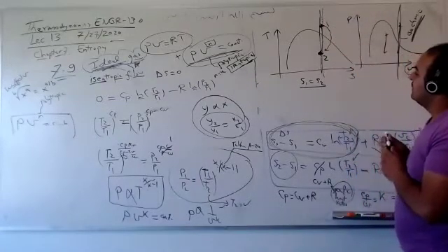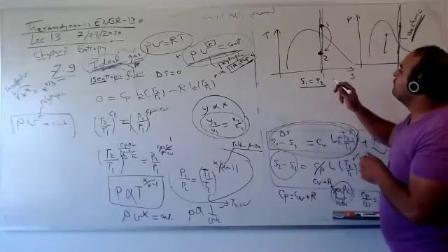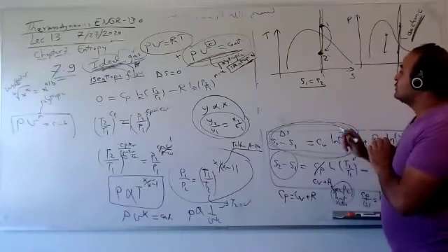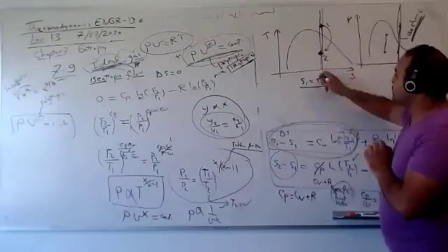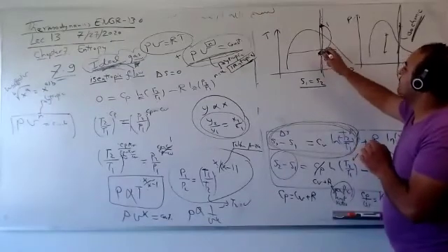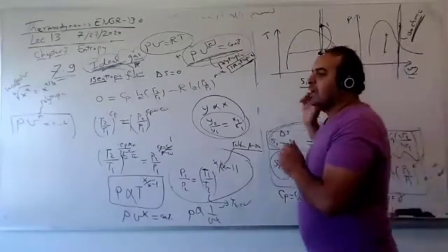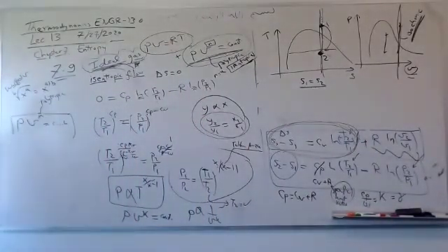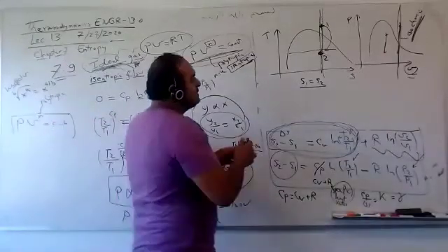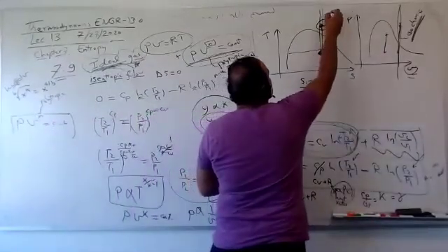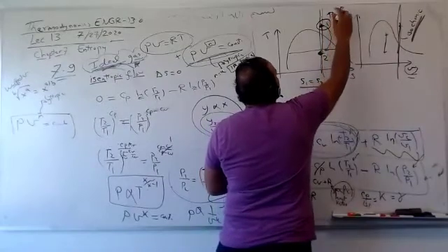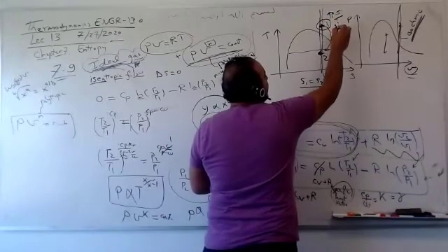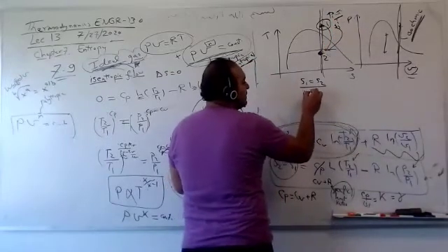state 2. It means I will not give more information in state 2. I will give you only one, let's say, for example, quality. So from quality and S1, which is S2, you can obtain everything here: the pressure, temperature, volume, internal energy, enthalpy, everything can be obtained at 2 if you only have another, because S1 equals S2. Any two independent properties, you can get one. One of these properties is S1. Give it to S2 if it is isentropic.